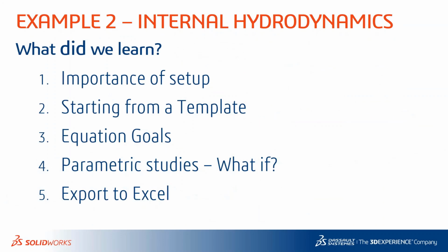All right, what did we learn from this hydrodynamic problem? The importance of matching the physical test setup to get good results. I started this problem from a template and how that can be utilized to expand it to other users who may not be expert users of the flow simulation. I defined some equation goals, and using an equation in another equation. I showed you how to do parametric studies in the What-if type and exporting that out to an Excel spreadsheet.